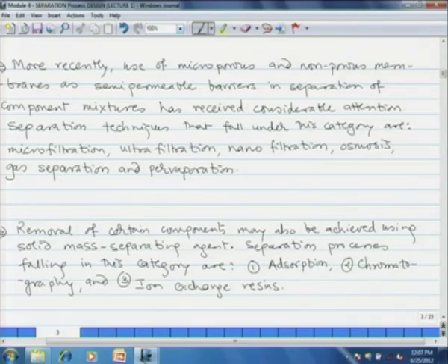In case of absorption, the particular component in the gaseous mixture is absorbed in the solvent. However, we need further distillation to recover this particular component and recycle the solvent. So, although absorption on its own could be less energy intensive, coupled with the distillation for the recovery of the solute, it becomes an energy intensive process. The advantage of these membrane processes is that they are far less energy intensive as compared to absorption and distillation. However, there are certain limitations of their own that we shall discuss later on in this lecture.